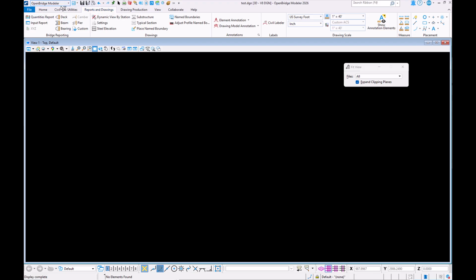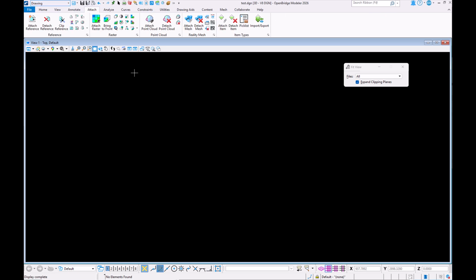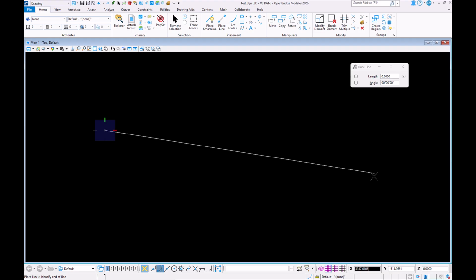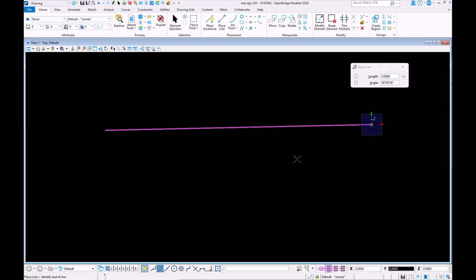Again, going to the basics one more time. Let's go to the drawing workflow. So basically, here are the MicroStation operations. We place a line, for example. So left click, data point. We place a line, left click, and left click, and we got a line. And the commands get sticky, so we keep placing lines. I can do that, or I can quit the command, so I can go reset, right click.